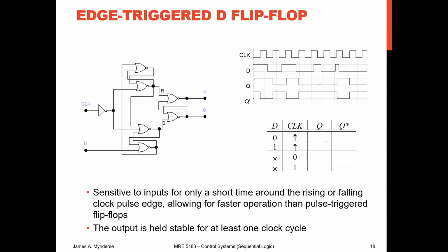Edge triggering is something I see a lot more use of because I think of edge triggering as being a great way to deal with clock signals that are nicely timed because I want to synchronize everything to operate on a clock signal. And so I might always go off of a rising edge, for instance. So in this case, look at that, we've got 3 different SR latches all combined together. These are all the same sort of idea here.